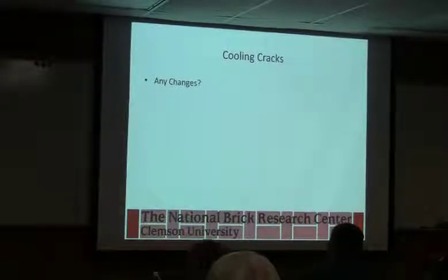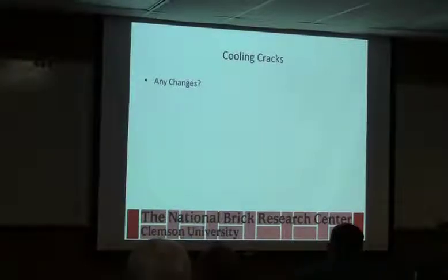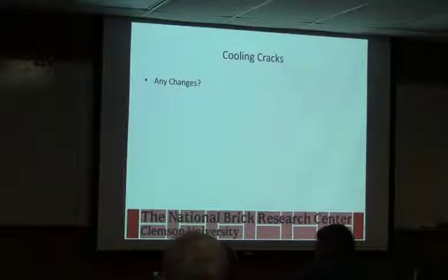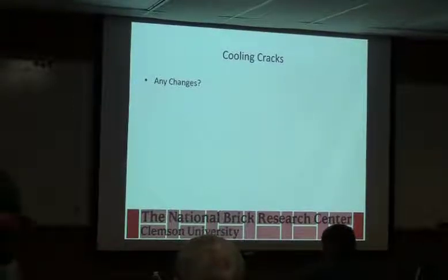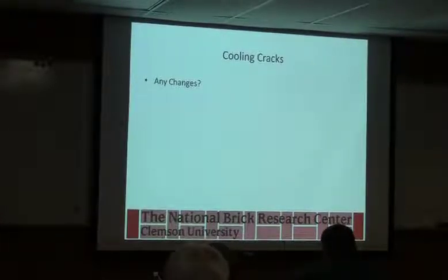So really, the best way is to slow it down. That's the typical response on quartz, to look at the rate, because coming up with a way of getting the quartz out or grinding it would change the particle size distribution of your product, and you may create a whole new bag of worms. So in more cases than not, it's either reducing the amount of that material that you're using, or looking at your firing curve to see if you can adjust it to compensate in this region.